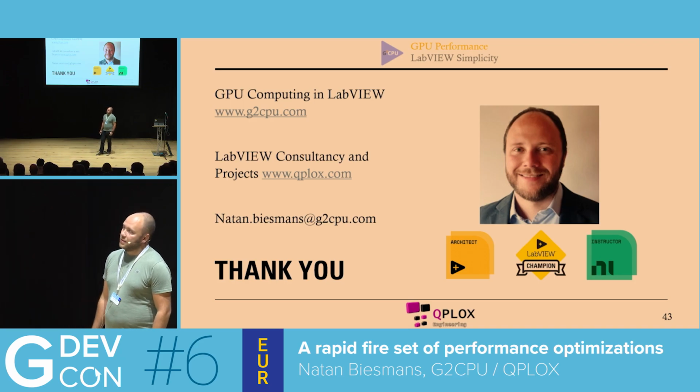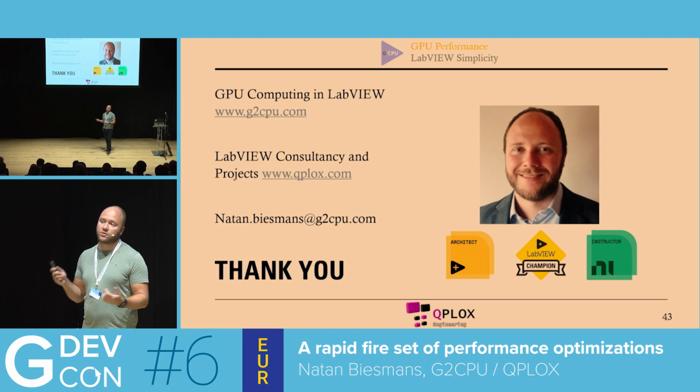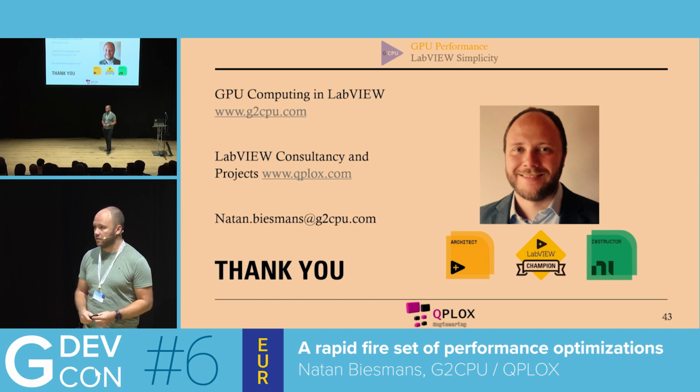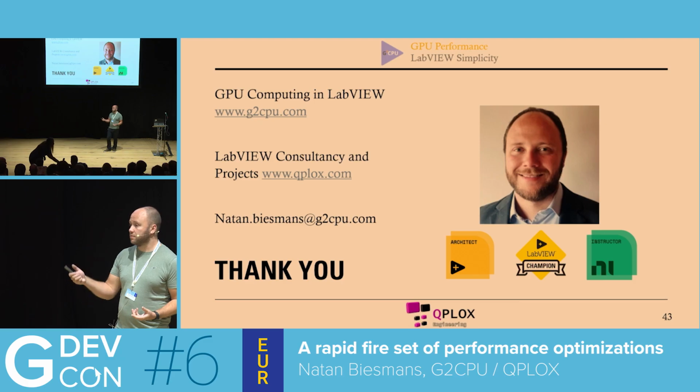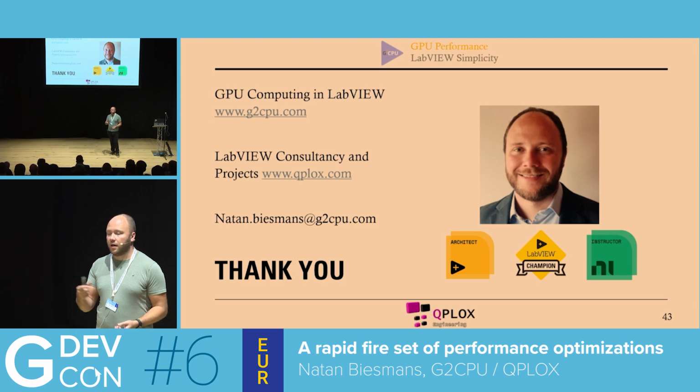Finding bottlenecks. The best way to do it is just benchmark it. I also encountered that a lot of the signal processing calculations within LabVIEW are just doubles underneath. And that does cause some issues. It happens from time to time that I get to a position where I need to transport it to the GPU, but maybe I need that low latency as well. So then I need to consider rewriting a certain function in LabVIEW to support single floating points. I've done that for quite some, for example, waveform functions. The waveform data type supports single floating point or even integers. But when you feed it into a lot of these waveform functions, they automatically cast it back to double floating points, causing quite some issues.